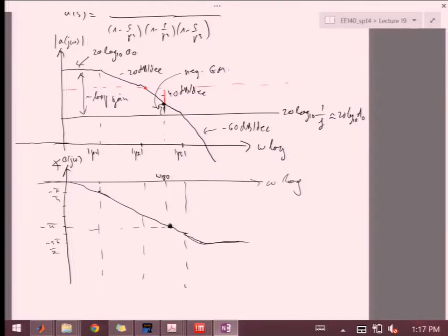Or in other words, if we look at where the crossing is, it would be here. So that's where loop gain is 1. And we look at how far away we are from pi. So in that case, this would be phase margin, that is roughly around 45 degrees, pi over 4. Right. So those were the basic definitions, how we analyze the stability.